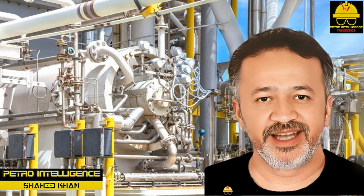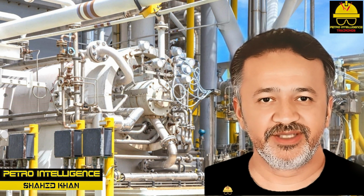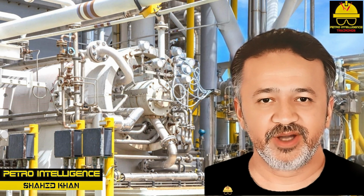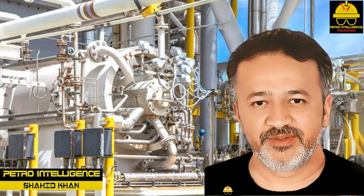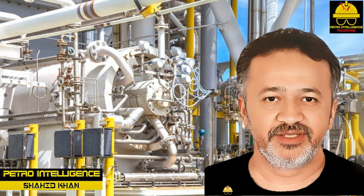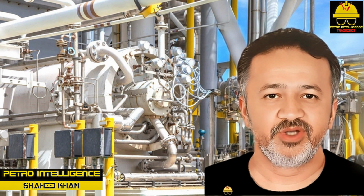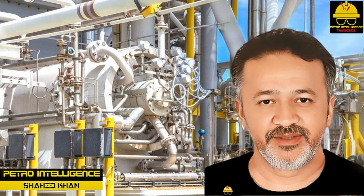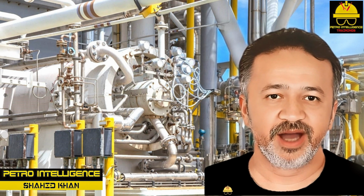Compressors usually can be classified into two groups: positive displacement and dynamic. Positive displacement compressors operate by trapping a specific amount of gas and forcing it into a smaller volume. These designs include rotary screw, sliding vane, lobe, and liquid ring, and reciprocating, piston and cylinder and diaphragm.